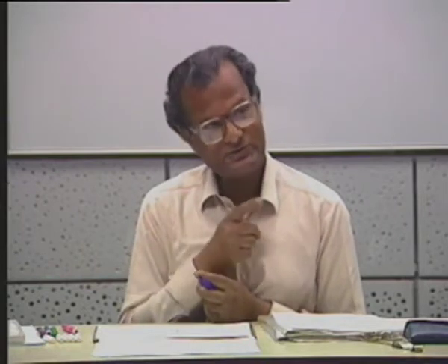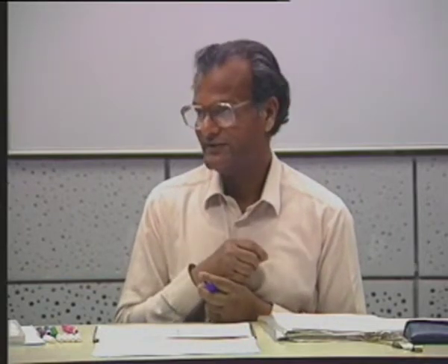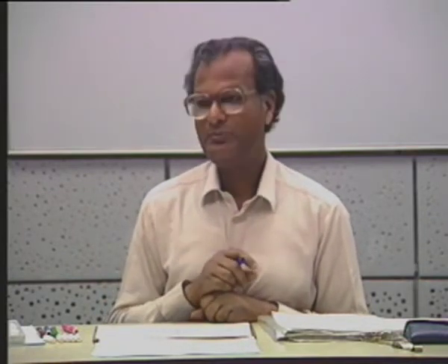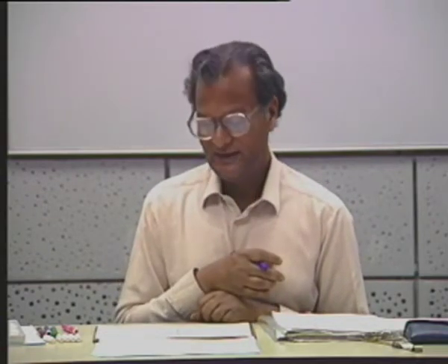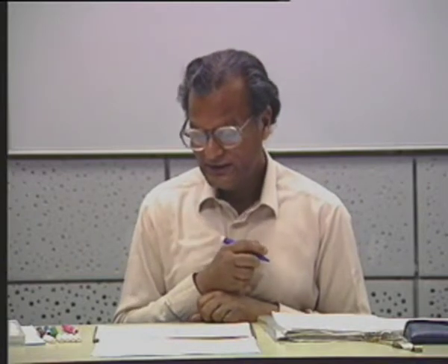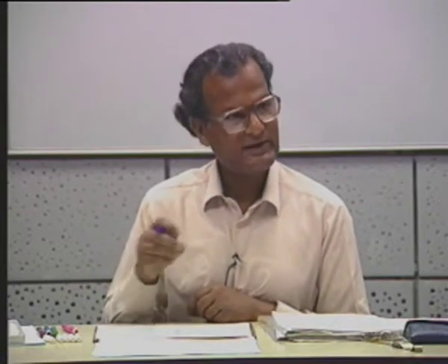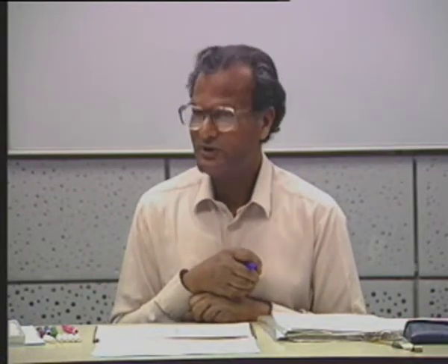A Zener diode can also be used as an ordinary diode if you bias it in the forward direction. On the other hand, suppose the doping is light. Heavy doping means that the electric field has ready access to covalent bonds which it can rupture. Light doping means it does not have ready access, and therefore in a junction in which the two sides are relatively lightly doped, Zener breakdown may not occur.